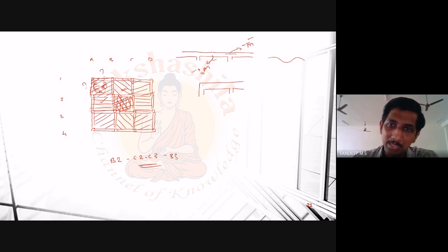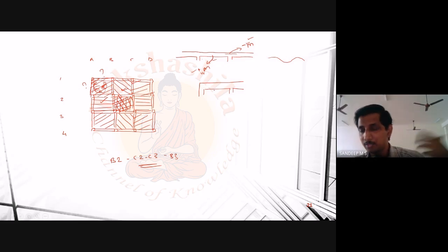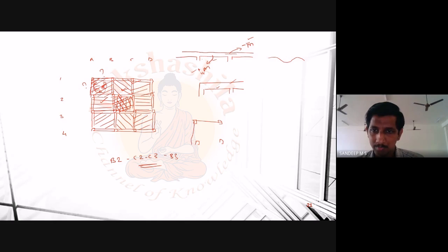But this will not be there if you have a discontinuous edge. At a discontinuous edge you will not be having any negative moments. In such a case you will be having only the positive moment at this mid span, but on this end you again have a negative moment. Suppose you have just 4 columns, and I am just keeping a slab on top of this.